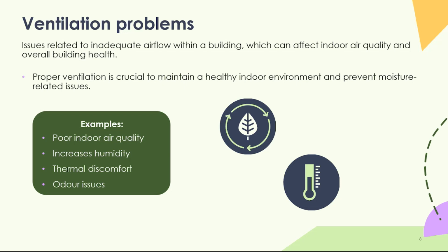There might be thermal discomfort because it gets too stuffy, or maybe there's too much airflow and it's too drafty. It could have odor issues. Poor indoor air quality as well if you've got gas burners on your hob, things like that. There are a lot of problems that you can worsen if you're improving the air tightness and the fabric of the building without addressing these ventilation concerns.